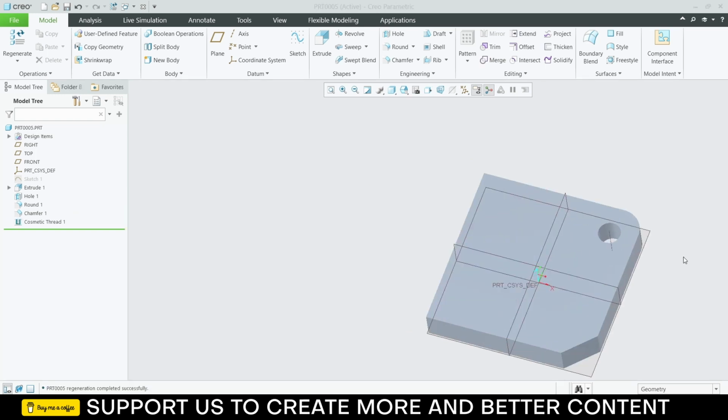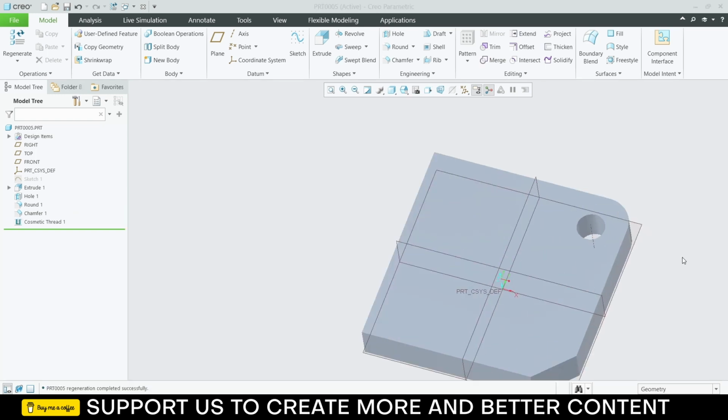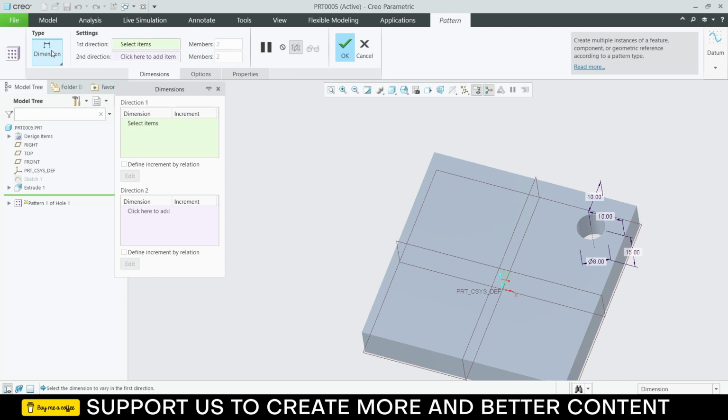Namaste guys. In this video, we will learn about pattern. As you can see, the pattern command is currently not highlighted because I didn't select any kind of feature. So let's say I select this cut hole. Now my pattern is highlighted. Click on this pattern. Now you can see there are multiple types. I will cover the first three. The rest of them will be covered in some exercises.